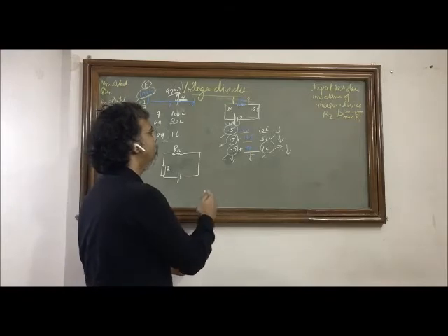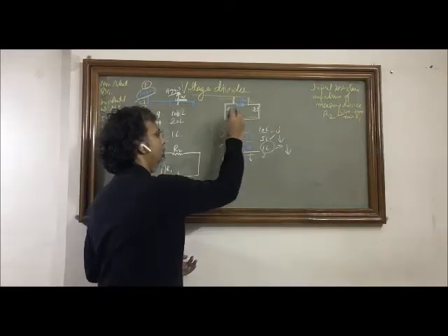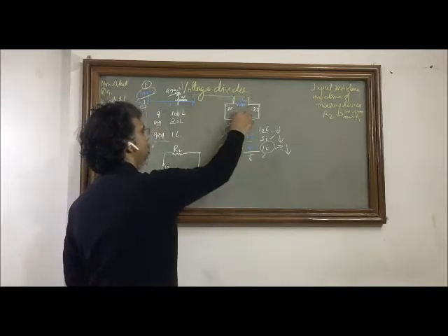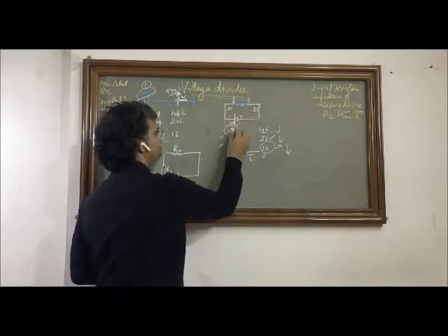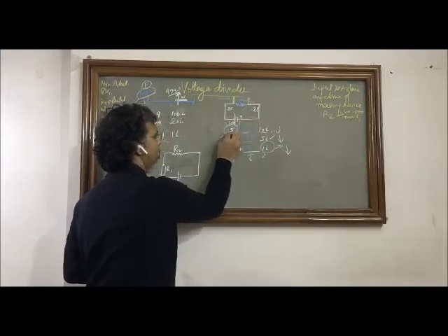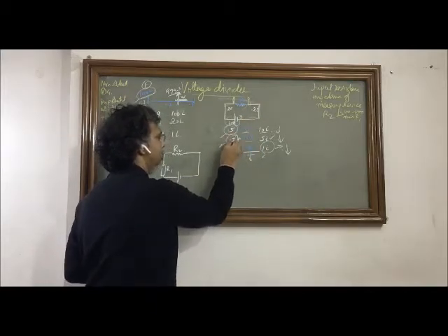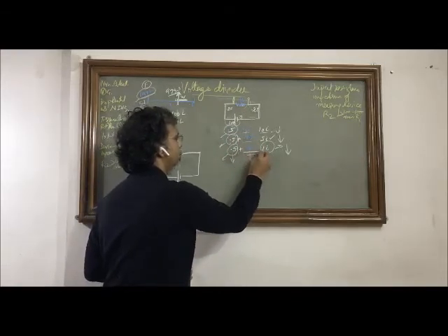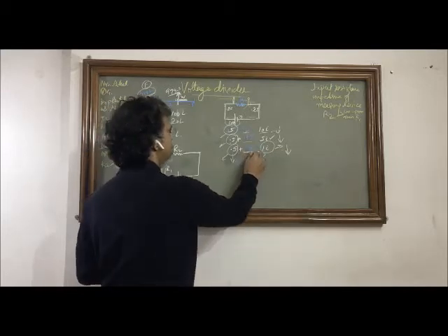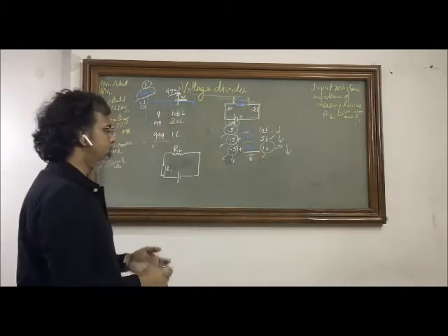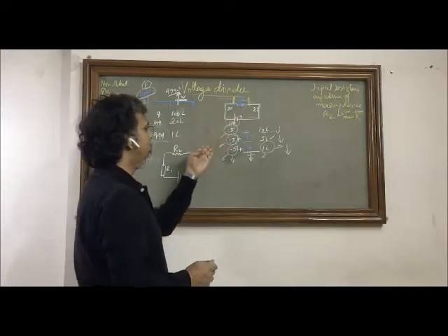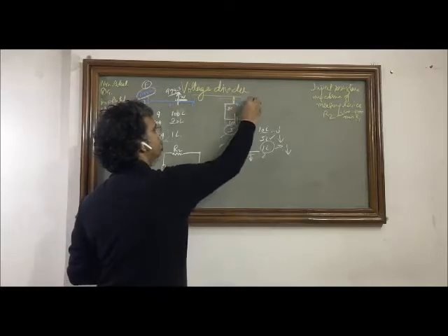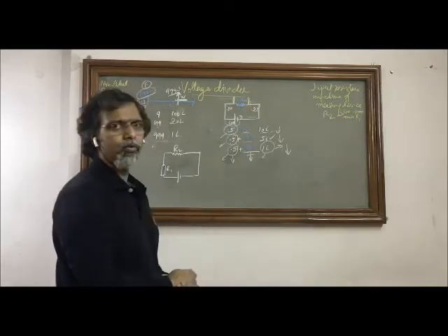And the percentage of the energy with which the electron, proton, or charge carrier starts increases as the value of R increases. Here you can see the percentage will be lesser because this is 0.5, this is 9.5. Here this part is the same, but this part is increasing. Here also this part is the same, but this part is increasing many-fold. So in this part, almost practically all of the energy with which the charge carrier has started is being consumed across this resistor only.